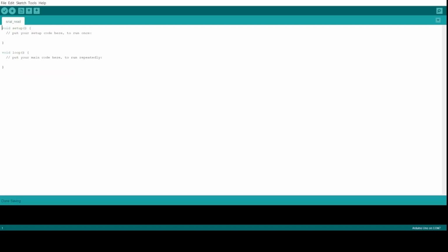First things first. This is what we'll need to do. We need 3 different outputs for the LEDs. Let me type int LED1. I want to put it on pin 6. Then LED2 equals 8. There we go. Int LED3 equals 10. So I declare all 3 of them.